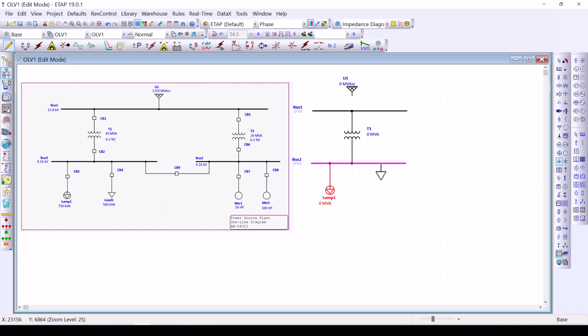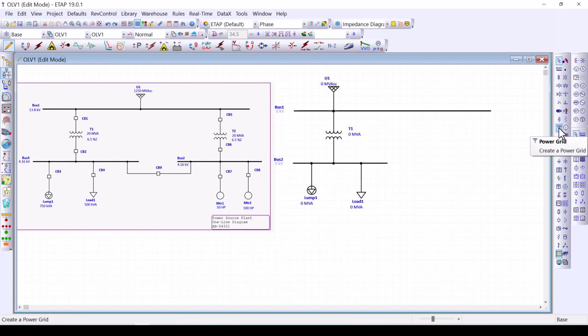Grab, hover, click, drop, and then let's create this portion, the right side. We can do that by extending that line here. And then we can add a power transformer, a bus, connect the sides of the power transformer, add two loads, and these are my induction motors.